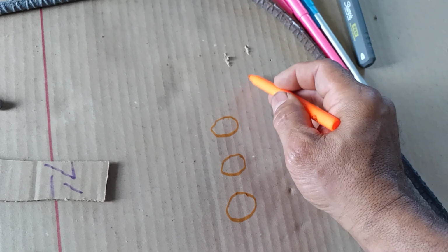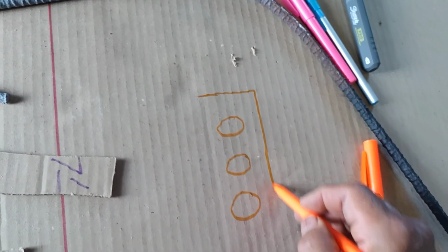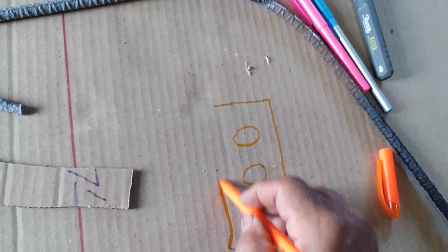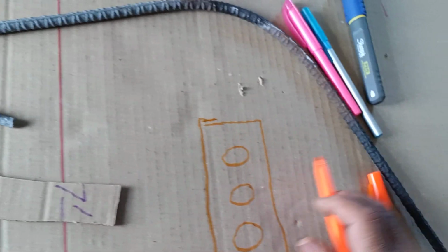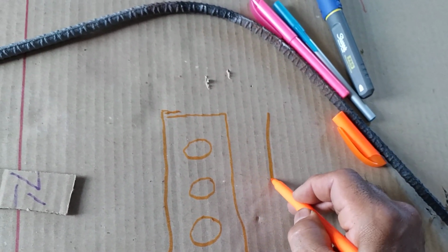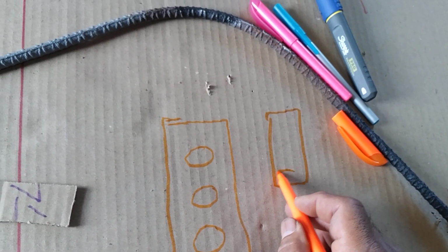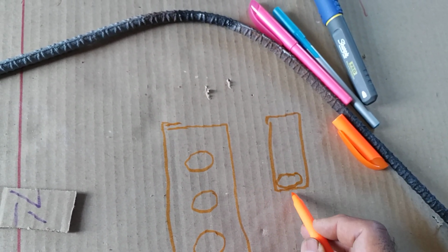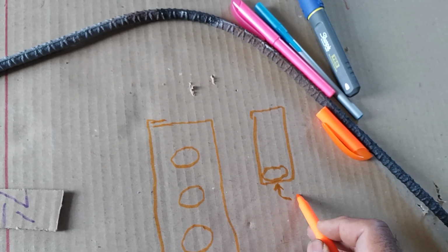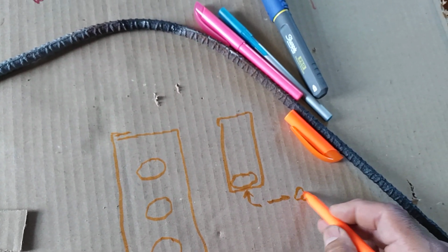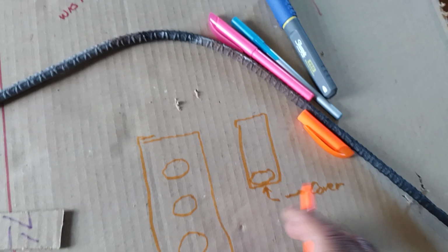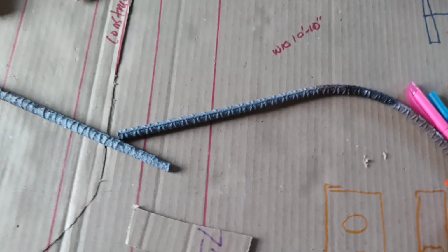But that's how it was supposed to be configured, and the thirds. So that's how it was supposed to be configured. In reality, it looks like we get this. We get, say, that same slab. It looks like we get it somewhere about here with very little cover. So minus cover. You get very little cover of one piece instead of a joint.